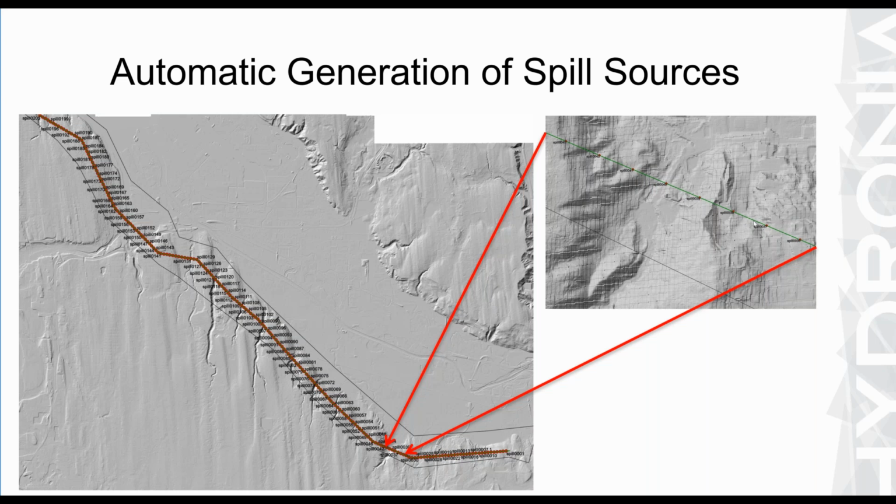This is a zoom in of this sector here. Each of these spill locations has a corresponding outflow discharge as a function of time. All of this is in the format required for the OilFlow2D model to run. So you get all of the details of the files already created, ready to run once you perform that computation here.